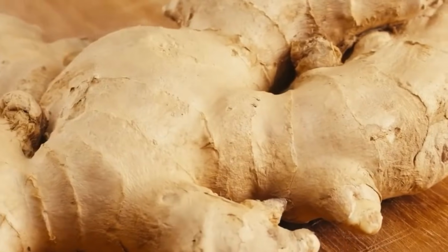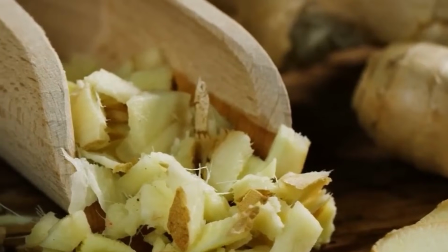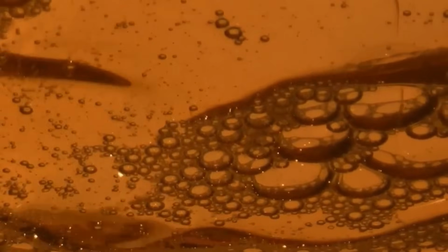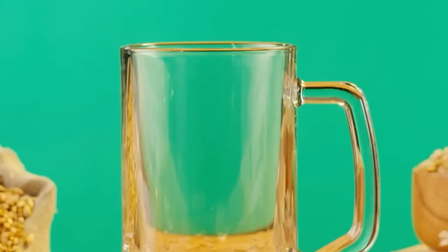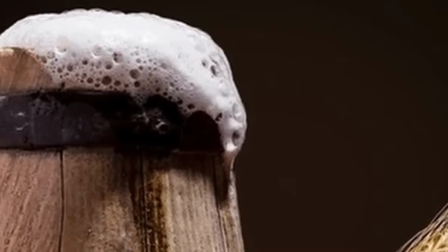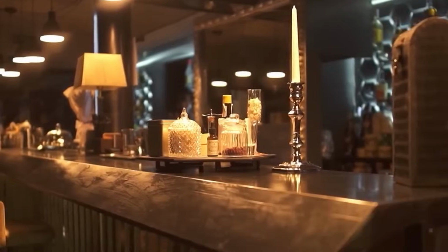Municipal water is directed into a series of pre-treatment systems through stainless steel pipelines. The first step is mechanical filtration, where water flows through mesh strainers that remove coarse particulates. Following this, it passes through a dual media sand and anthracite filtration system to eliminate finer suspended solids.